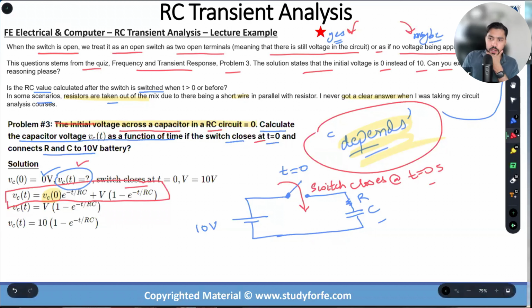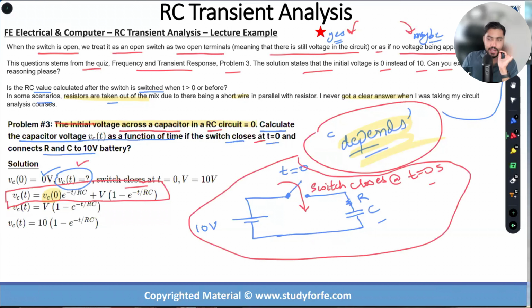Okay. Now, if I don't do anything with this circuit moving forward, just take a second to absorb what is shown here. Just take a few seconds to absorb what's shown over here. Pull up the reference handbook, go to RC Transient, look for equations and circuits. Will you be able to connect the dots? Should be. This is an equation that applies to this. Now let's look at what is given to us. VC0 is equal to 0 volts. I'm just going to make this 0. And all I'm left with is this.